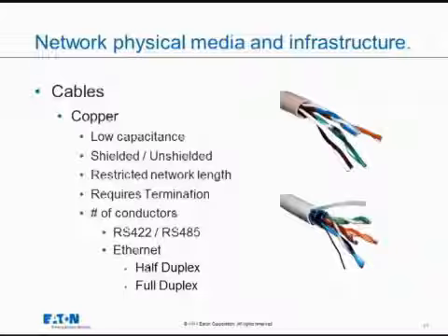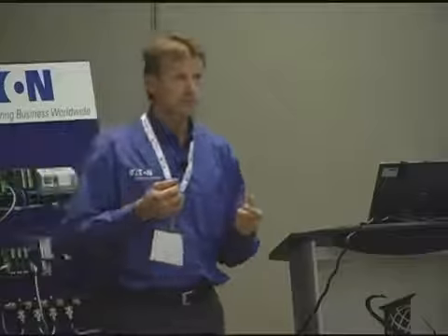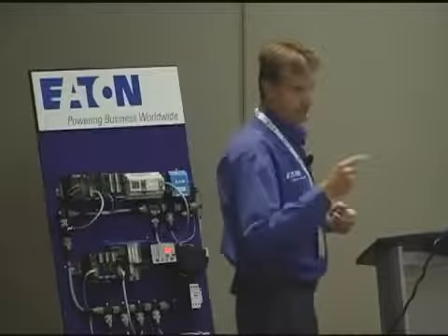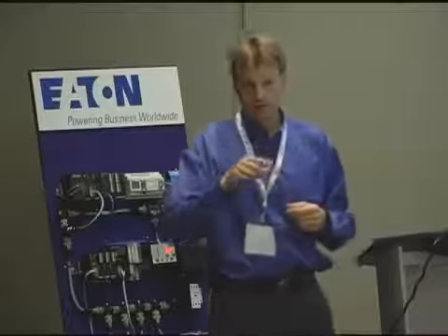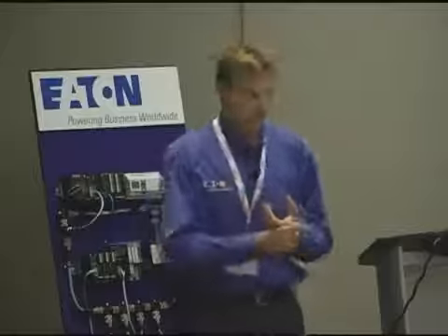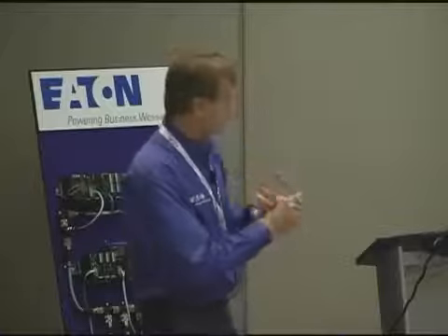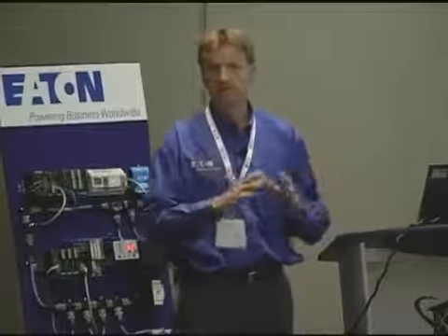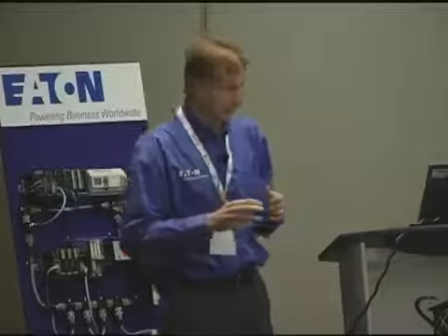Low capacitance. A network is a form of communication where it typically uses digital communications. So we have a binary string. So how we communicate is with voltage levels, by putting a square wave of voltage levels. We have ones and zeros. A 1 being a high voltage and a 0 being a low voltage. Now we send that out at different frequencies depending on the protocol.